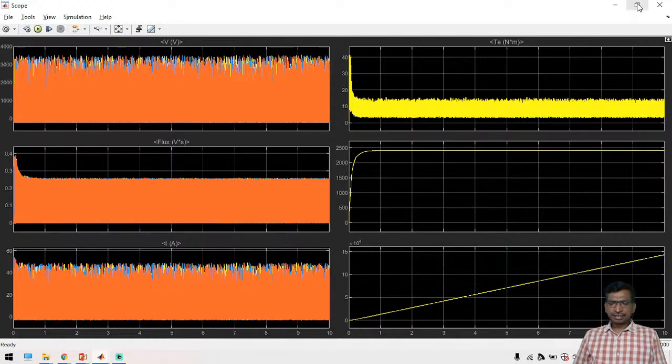The major disadvantage of the SRM motor is the vibrations, because this motor will generate huge vibrations. Suddenly we are switching on one phase, and then we are changing to the next phase. Then the rotor will move from its original position. The rotor should work on its moment of inertia. Due to that behavior, the motor will create huge vibrations and also heavy noise.